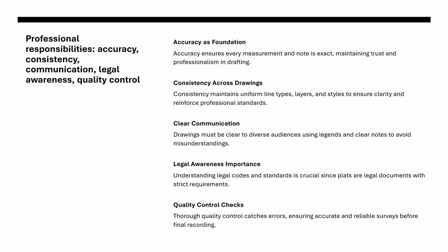Fourth comes legal awareness. I told you then, and I will repeat it now. You may not be the one sealing the plat, but you need to understand the rules outlined in the Texas Administrative Code and how the board enforces them. Legal awareness means knowing that a plat is not just a technical drawing, it is a legal document. Board rules in the Texas Administrative Code, Title 22, Chapter 663, spell out what must appear on plats, how surveys must be certified, and what standards apply.